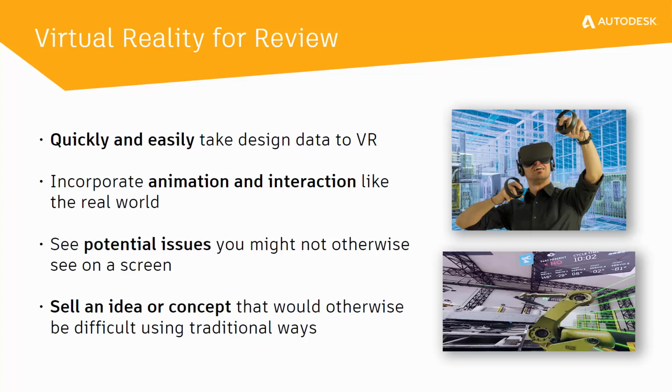And furthermore, virtual reality is another means by which we can review our factory designs as part of this workflow. Now, for those of you who caught my webinar prior to Christmas, hopefully you will have seen it's very quick and easy to be able to create a VR experience using 3ds Max Interactive, using assets that are coming from the likes of Inventor and Fusion. Here we can create not only this VR content quickly and easily, but we can animate it and create interaction with it so that it reacts and interacts in much the same way as the real world does. Hopefully this enables you to find potential issues that might otherwise not be able to be found if we were just looking at it through the screen.